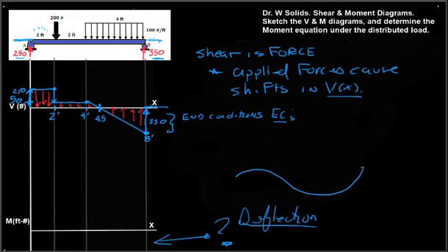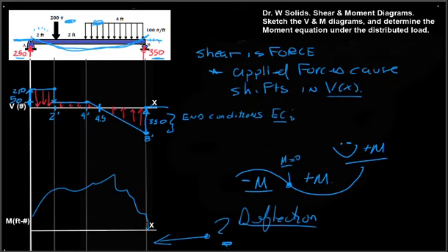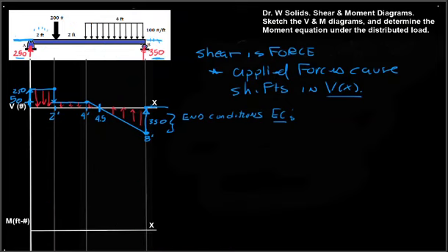If the beam is bending, point of inflection, you'd have M equal to 0. And happy faces are caused by positive moments. If we look at this beam, for this load configuration, I can see the beam is going to deform something like that, in which case it's going to be quite happy over the whole region, and I anticipate this being a curve that looks like that. If this support were further in, it might curve like that, in which case this would do something like that down here. So this moment curve should have all positive values.